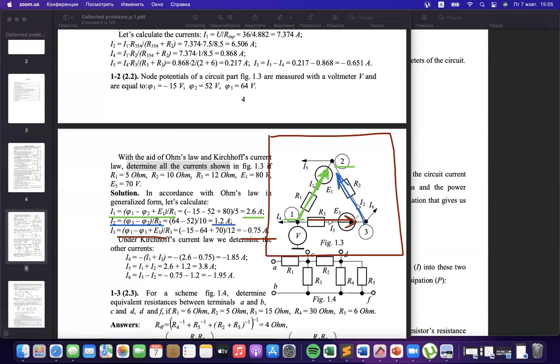That means the current will flow in the opposite direction. Everything is okay. If you obtain a negative value, it is normal. You just know that the real direction of current is opposite. But mathematically, it is the same as current in this direction, but with a negative sign.